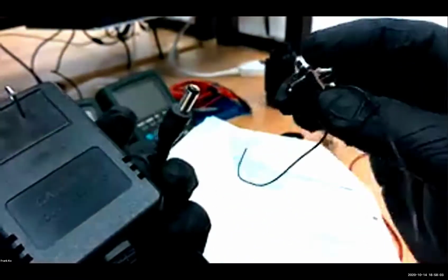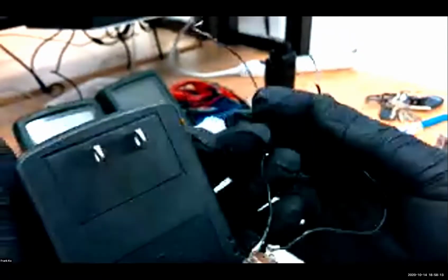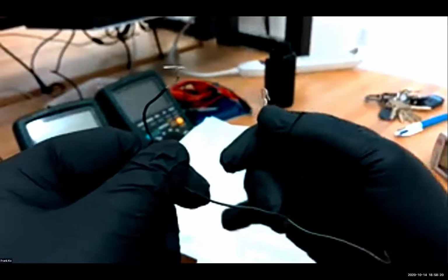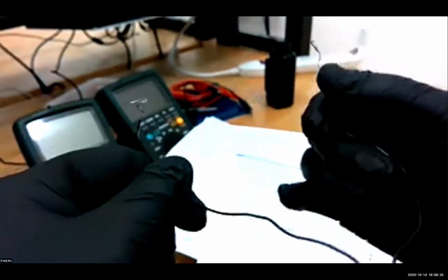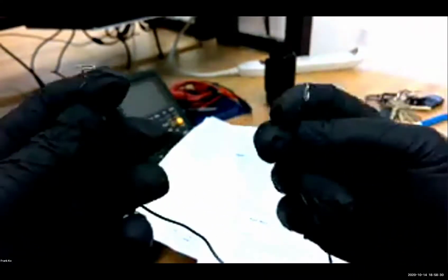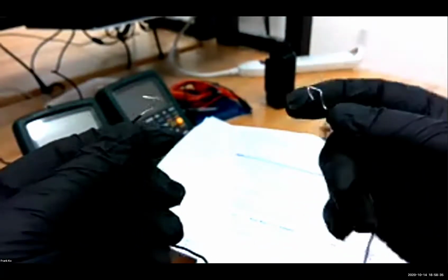To make things easy for you, Nabil has fashioned from previous labs this particular adapter, and this adapter plugs right in here, and it has two wires for you to use. There's a wire here, and a wire here. Do not, under any circumstances, touch these two wires together. It would be catastrophic. It would lead to automatic destruction of the transformer and possible injury to yourself. Do not handle the bare wire ends of these without using your insulated rubber gloves, latex gloves, nitrile gloves.